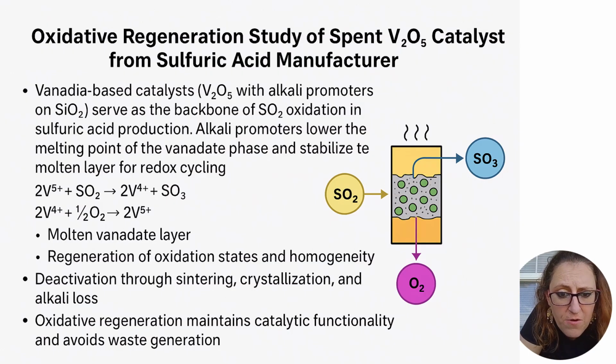mass transfer limitations. Over time, vanadium pentoxide catalysts deactivate through sintering, crystallization, and loss of alkali promoters. Prolonged exposure to hot acidic gases causes phase segregation in the vanadium alkali silica matrix, leading to decreased surface area and activity.